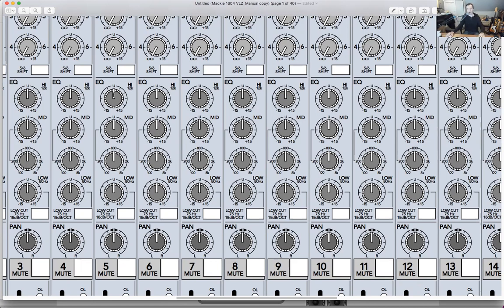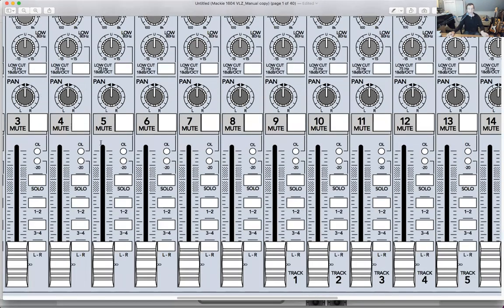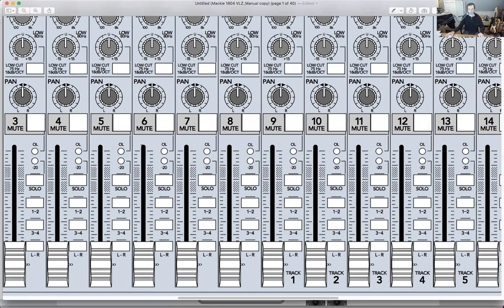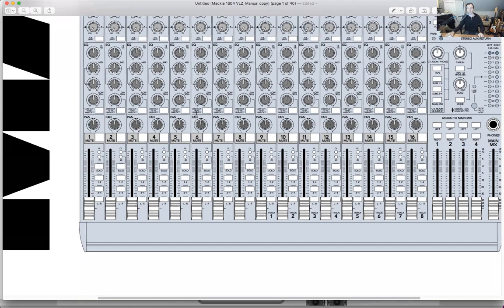But also, if we take all of these knobs on an EQ and turn them down, well, we've just lowered the entire signal essentially by like 12 to 15 decibels. So now it's too low. And how do we get it back up? Well, we've got to, I guess, crank our fader up really high. Well, now what if that signal needs to get louder? Well, we have no way to do it, right? Because we messed up our gain structure. So that's a basic idea of gain structure on this specific console and how you might approach those two concepts of gain structure and signal flow.